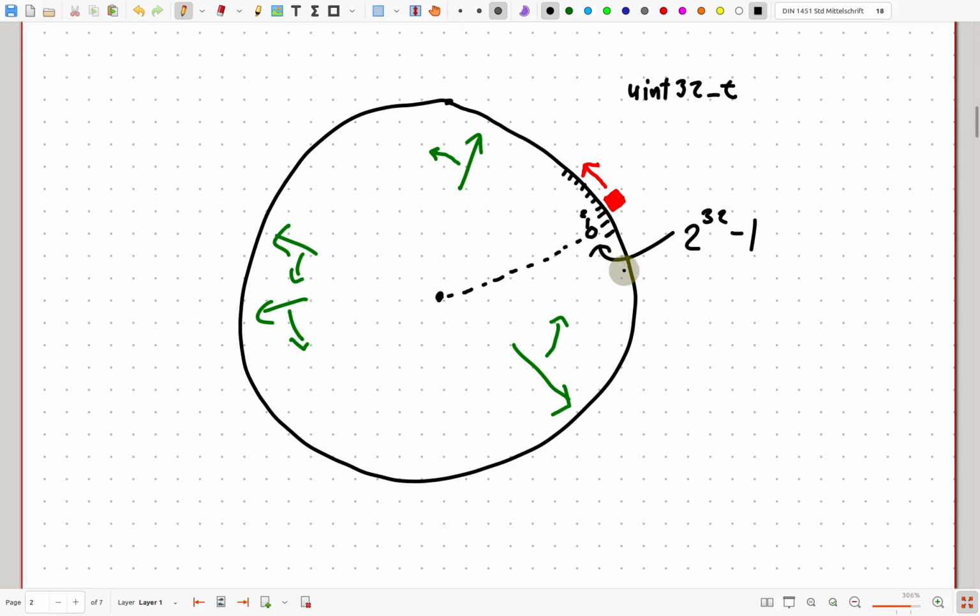We've got how many samples are in our buffer, which goes from 0 up to some number, but that number is at most something around 96,000. But I think we also want to do the manipulation of where these playback heads are in this unsigned integer space going all the way up to 2 to the 32 minus 1, and then we'll convert it back into the smaller numbers used for the actual samples on the tape later on.